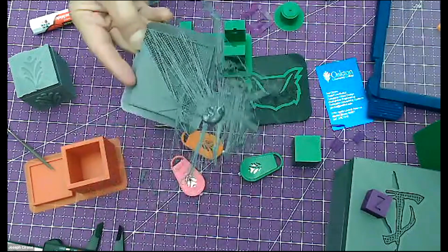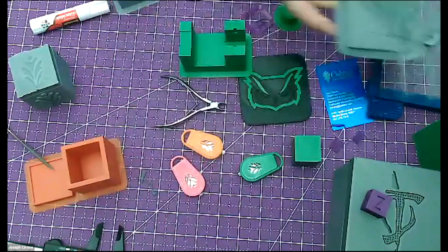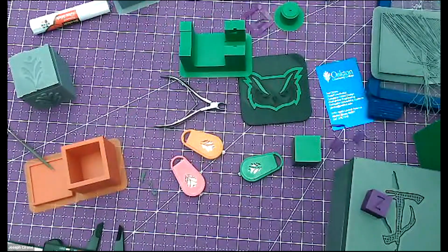As we start to work with these different projects, the materials will have different melting temperatures and extrusion rates. The way they work on the Bosch Dremel and the Ultimaker machines is that the material is chipped with an RFID chip, radio frequency identification tag, I don't know, device. And so it talks to the printer, just like when you go through the iPass in your car, there's a chip in there that reads a signal sent out, and then it calibrates based on that. So materials are probably the next big thing, Al. And right now we're just working with polylactic acid, or PLA.